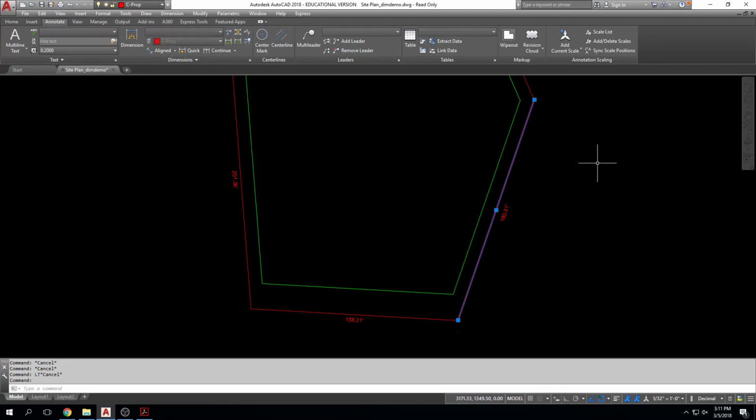Hey, Shelly. It's not showing up, the text on mine. Your dimension style, set dimensions, and line dimensions. And you changed this to that, right? There you go. Okay, so that's tricky. He dimensioned his, but didn't have the correct annotated scale, and it was invisible, essentially. Well, it was likely really just tiny.